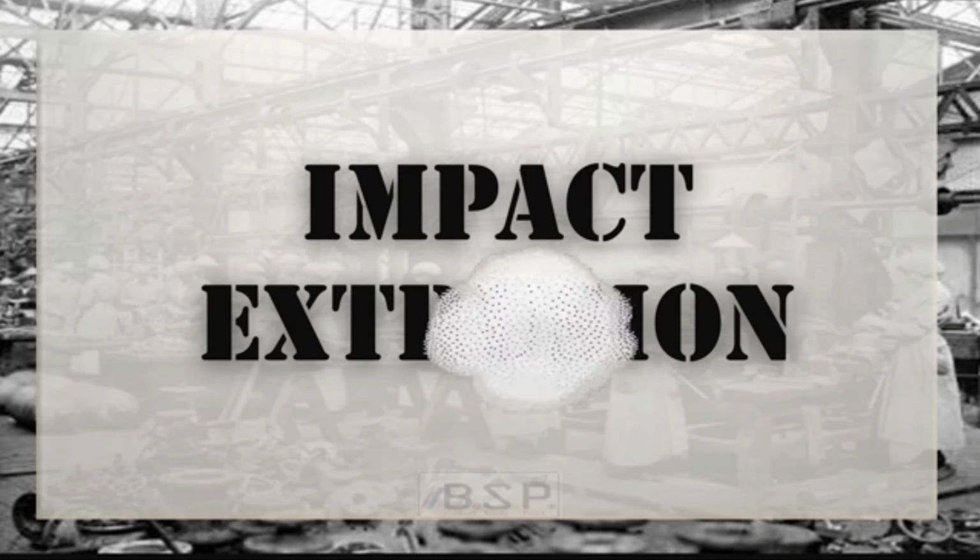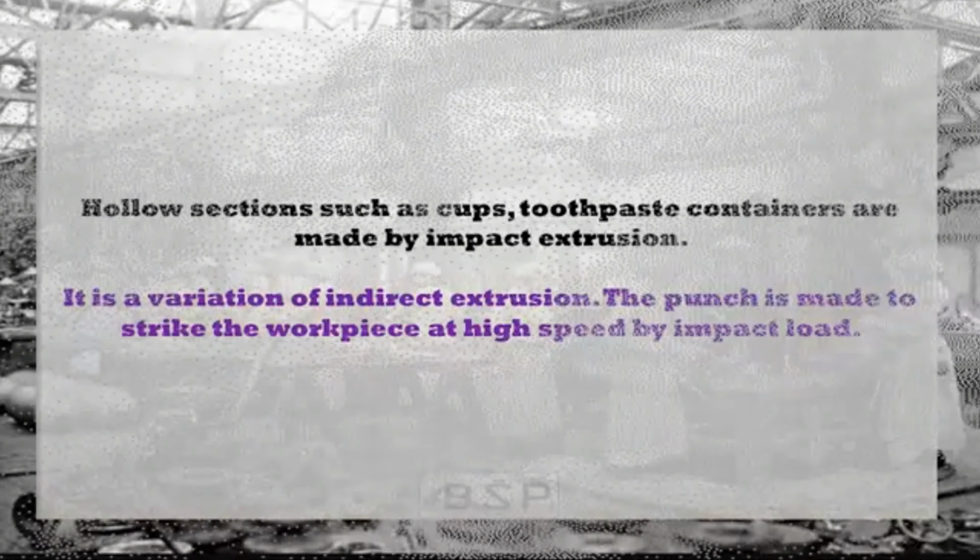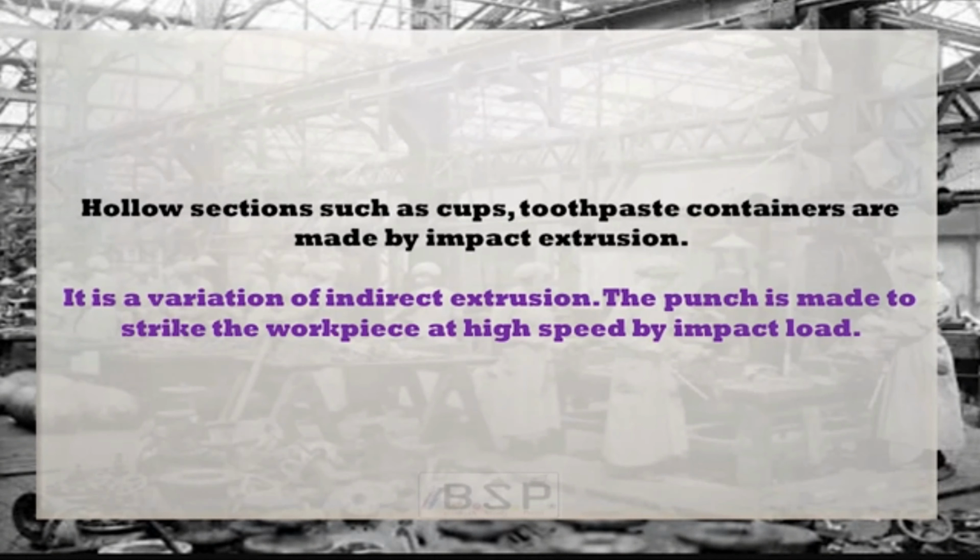So now let's move on to the last part, impact extrusion. Impact extrusion is a manufacturing process similar to extrusion and drawing by which products are made with a metal slug. The slug is pressed at a high velocity with extreme force into a die or mold by a punch. Hollow sections such as cups, toothpaste containers are made by impact extrusion. It is a variation of indirect extrusion. The punch is made to strike the workpiece at high speed by impact load.